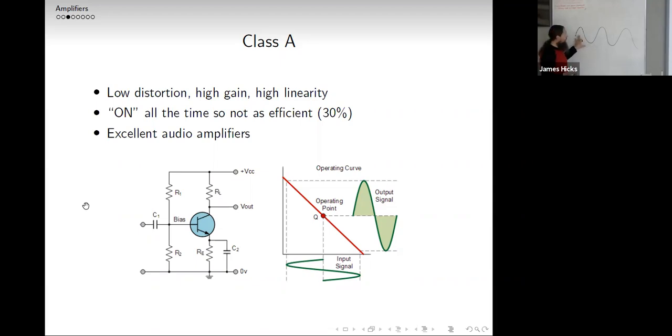You want a faithful reproduction of your frequency. A nonlinear amplifier is just what it sounds like. You would have some component that would be proportional to maybe the square of the signal. So if you got to higher signals, higher amplitudes, maybe you got more gain. Or maybe it's nonlinear in the opposite way, where as you go to higher amplitudes, the gain's not as good. That would give you a distorted output.